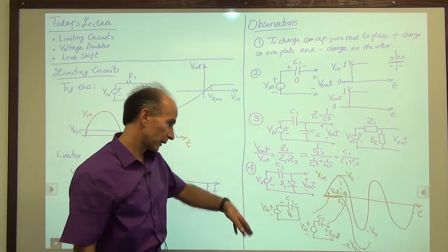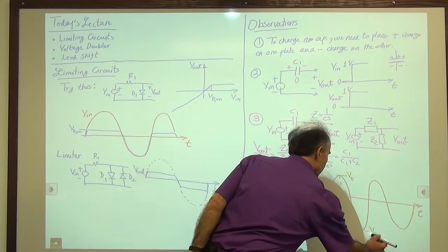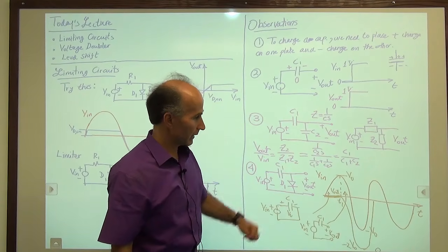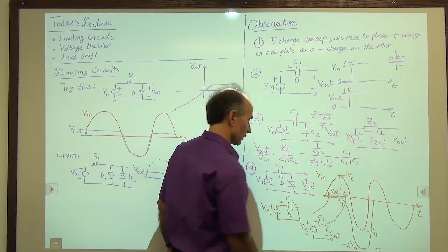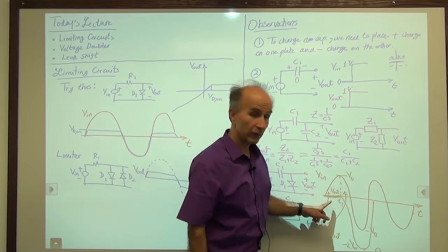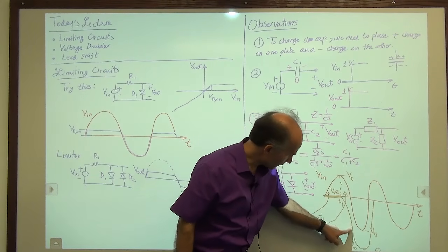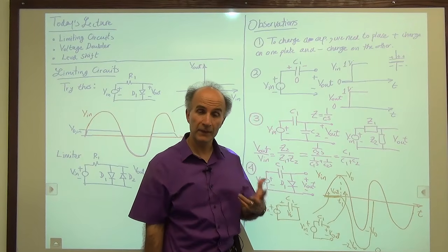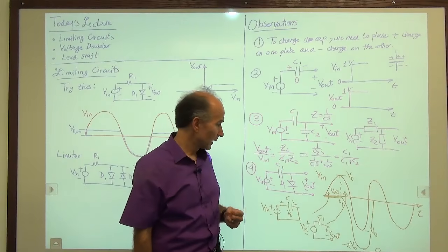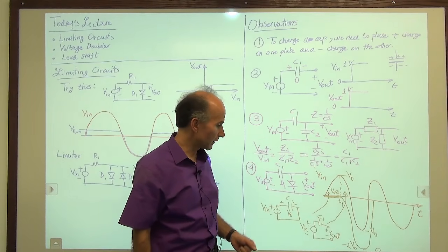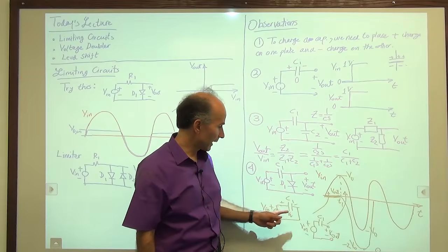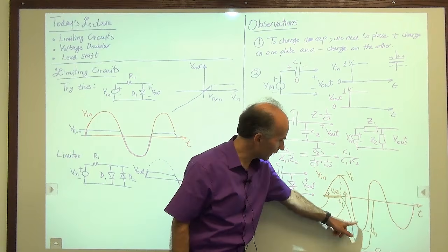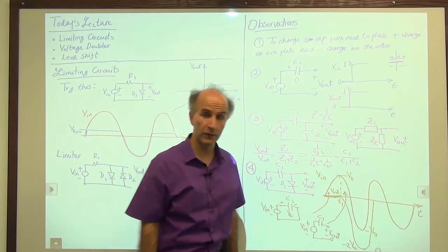All right, so now the input goes back up, and this goes back, and so on, and we won't worry about that too much for now, but that's what we get. The key point I wanted to convey is this behavior here, which is very interesting and very different from what we have seen in the past. The capacitor was charged to V0, so that the output is 0 when the input is V0. And when the input starts falling, the output also starts falling to minus 2 V0.